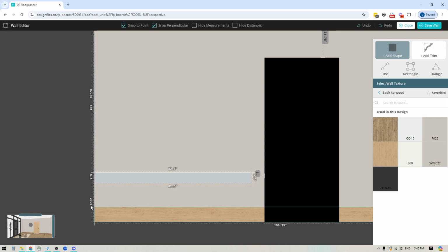Now what I want to do is bring this down, because technically this would be 26 inches from the floor. That's a bit high. So I'm going to click my rectangular shape here, and I'm just going to use the left, right, and up, down arrows on my keyboard, and I'm going to drop this down so that I've got 14.5 and 5. So the top edge of my bench is going to be 20 inches. I'll leave it at that.